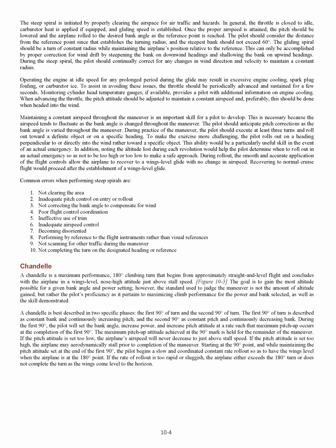Once the proper airspeed is attained, the pitch should be lowered and the airplane rolled to the desired bank angle as the reference point is reached. The pilot should consider the distance from the reference point since that establishes the turning radius, and the steepest bank should not exceed 60 degrees.